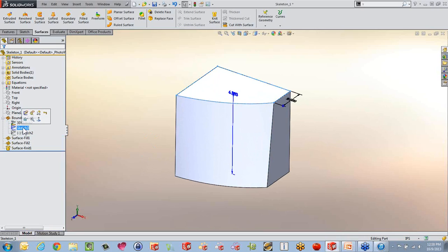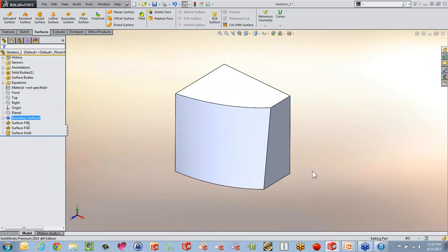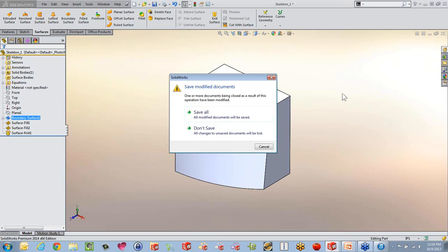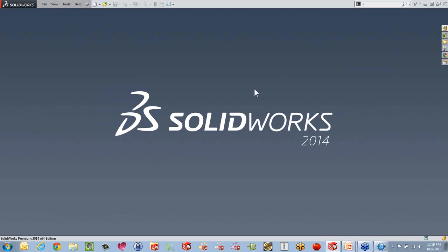Because if I go into my sketches in here where I have some dimensions, I placed it like that. So surfacing like that can be a good alternative when it comes to working with surface inside of SOLIDWORKS. So think of it like what you know, what you have, and you can build these frames up and again create a solid model like this, and you now have the true model of what you want instead of trying to, I want to say, cheat your way through it with the solid bodies here. All right, so just a couple of examples. Just wanted to show some of the different things you can do with it here.